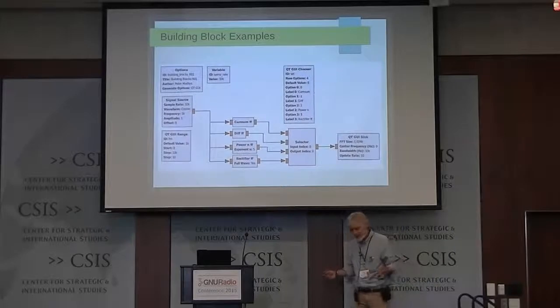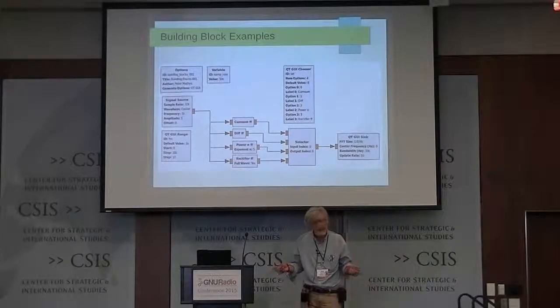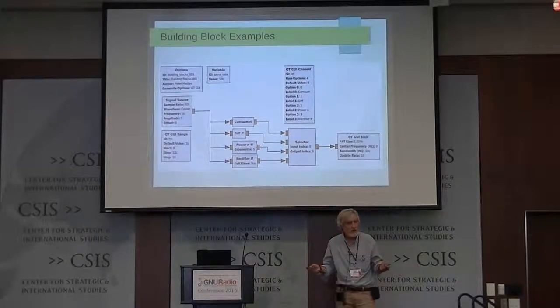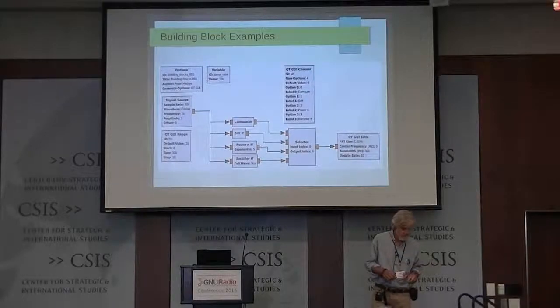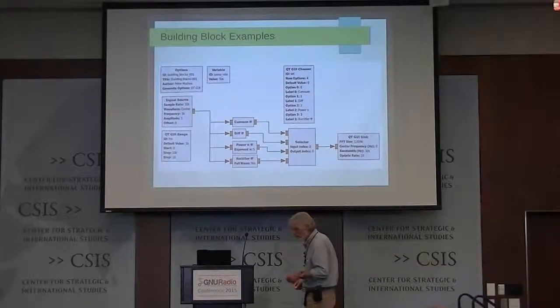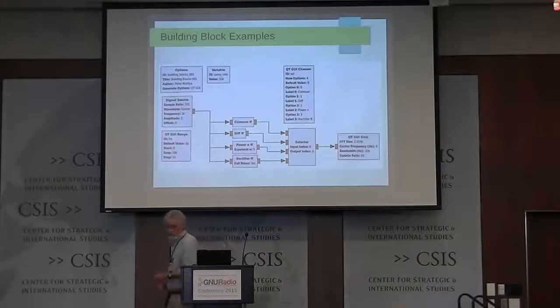The nice thing is, when you use the complex exponentials and raise something to the fifth power, it simply shifts the frequency over to 5 times the frequency, whereas if you do that with the cosine, then you get all kinds of products between frequencies, and you don't only get 5 times the frequency.